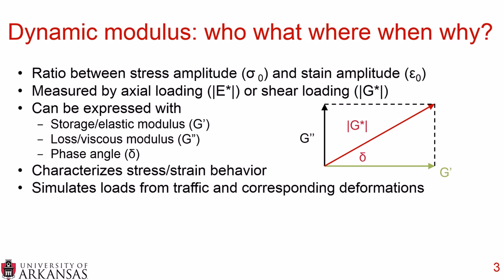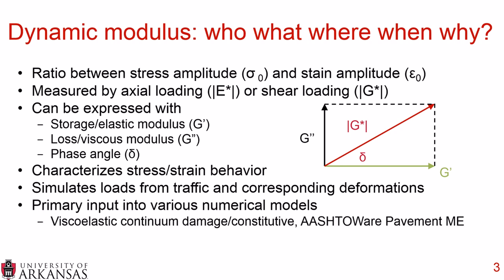Now, what can dynamic modulus do? It can characterize stress-strain behavior, and it can simulate loads from both traffic and the corresponding deformations from that traffic. It's also a primary input into various numerical models, including multiple viscoelastic continuum damage and other constitutive models, and also the largest is the AASHTO Pavement ME. Dynamic modulus is a key input to all of these numerical models.